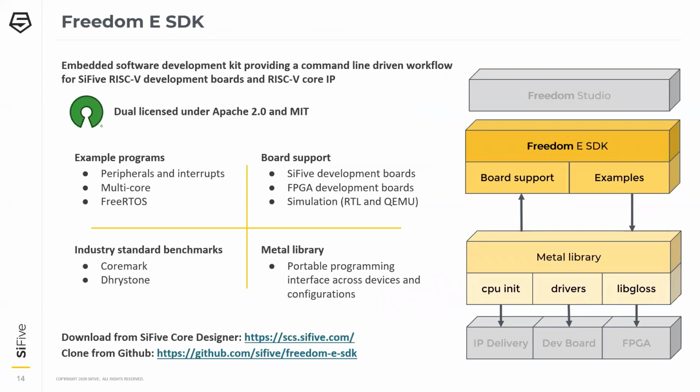In a silicon design cycle, benchmarks are important to see how your design is performing and how you are improving or regressing the design. Of the examples, CoreMark and Dhrystone benchmarks are provided, so you can quickly and easily evaluate your design and compare it to something in silicon, and then model how it might end up.